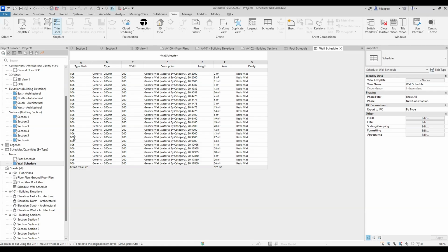I can tell the client that. Having the area in square meters, let's say you have 2 square meters for 1 block, you can divide to get the number of blocks. That one is another topic for discussion. The people who do these quantities and surveying, the quantity surveyors, know what 1 square meter of a block contains, the number of blocks. So you can always get that value from them. Then you just multiply by it.